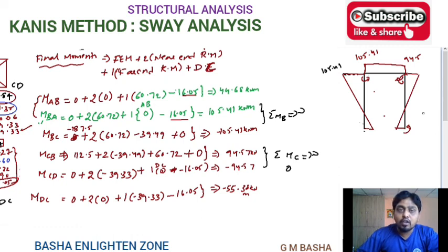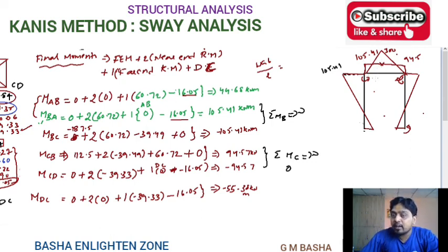And automatically we know that whenever an eccentric load is acting exactly at the point load, you will get a triangular variation. You can find out this maximum bending moment using WAB by L, which will be around some 300. So find out the ordinate point exactly for this 3 meter span. I already solved so many net bending moment values in the previous problems, so check once, you will see how to solve the net bending moment values also. I hope you understand this lecture.